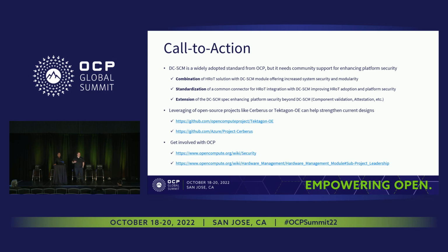We'd also want to leverage SPDM and other standards out there to do better attestation. Of course, you could do bit banging and hashing and reading for people who don't want to follow standards. But the better way is there's some inherent security they build into their side, and you can validate that it's properly responding to nonces on the other side and everything like that.